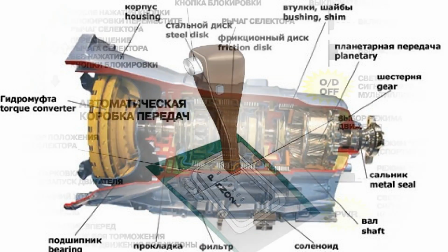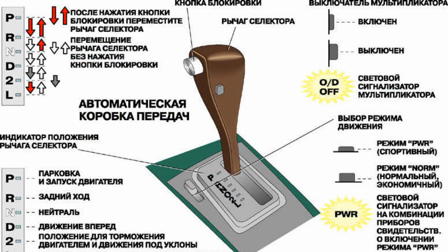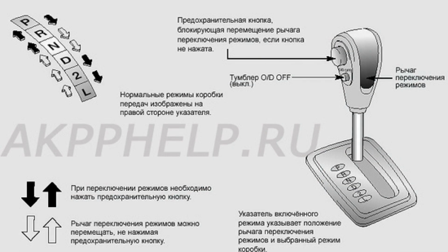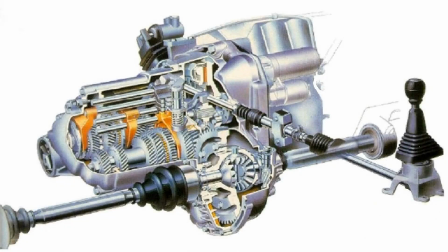Whereas a manual transmission requires the driver to manually change gear ratios, an automatic system does it all by itself, using fluid pressure. Automatic transmission fluid provides the pressure needed to activate the clutches and bands that determine the vehicle's gearing. The planetary gear is responsible for changing gear ratios. It comprises a sun gear surrounded by small satellites enclosed in a ring gear. Phew, that was a mouthful.